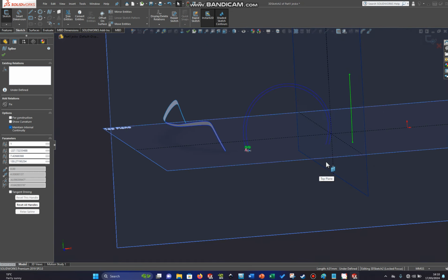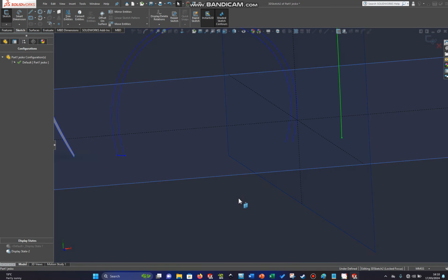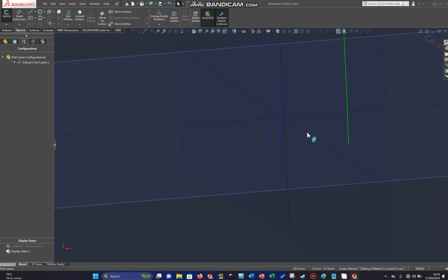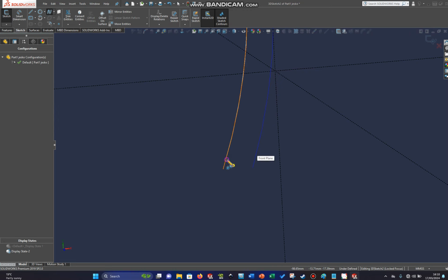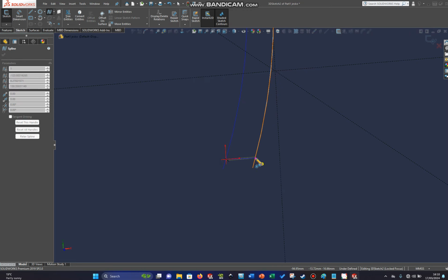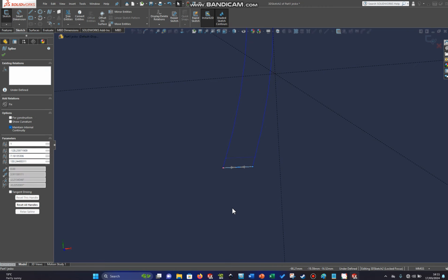That means that we have a coincident edge relationship with each other. So they clicked onto each point. They locked in, kind of. You can say they locked in. Okay, so let's get this other curvature. Same thing here. Just drop it on these lines, and I'm just going to pull this until I see the green check marks.